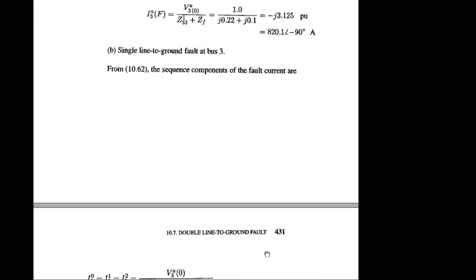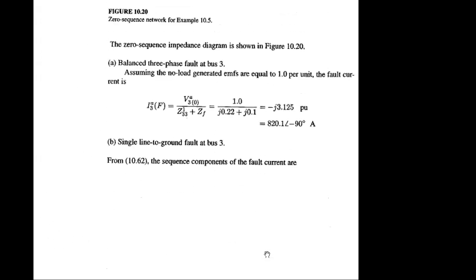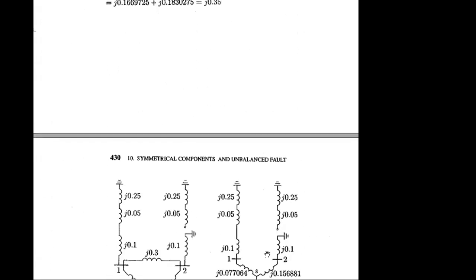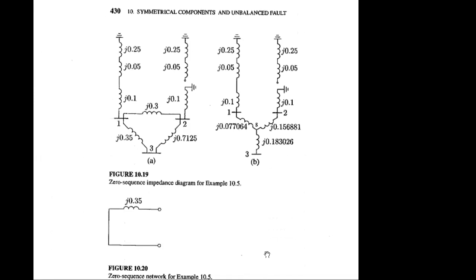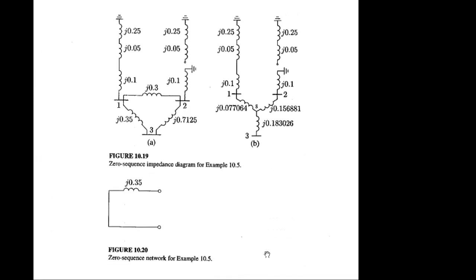Actually, this problem requires a two-step solution. First step is to generate the Thevenin equivalent impedance to address different Z. Second step is to determine all the fault current in terms of different configuration. That's the final or total picture of this problem.